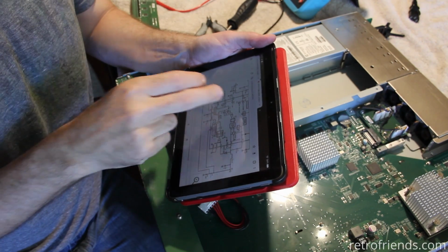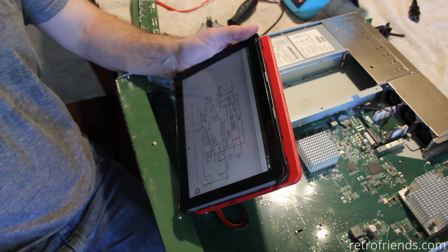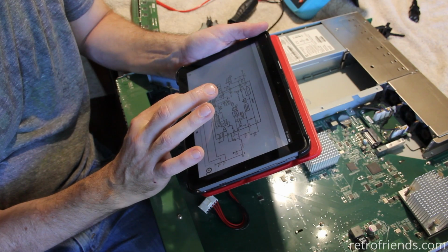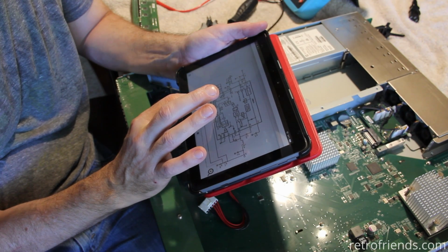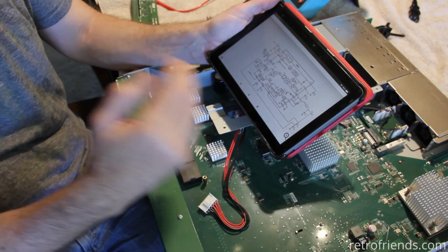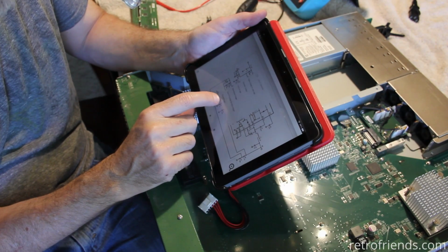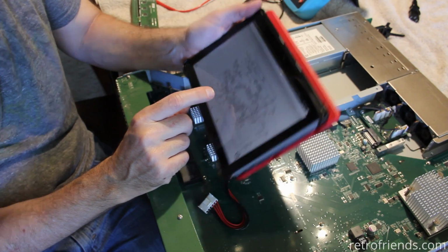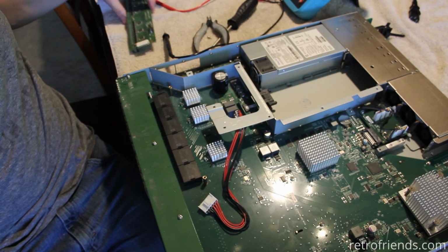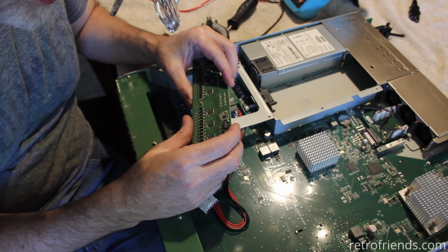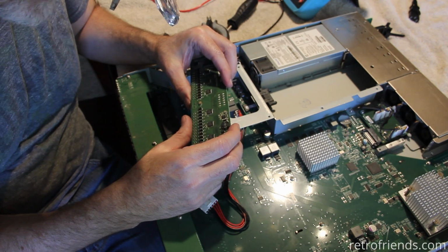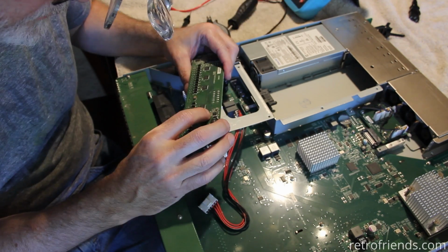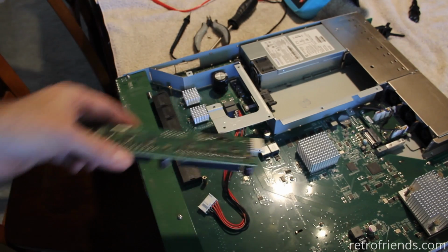I mean, that thing was tiny. But hey, you're putting 56 volts into it. Pin 4 is the sink, and that kind of looks like the pin 4 side of it. So maybe 56 volts went into pin 4 or pin 2, and that would have done it. That stupid little solder ball. That thing was pretty microscopic. Wow. All right, well, that points me in a pretty good direction. So I'm going to order another one and replace it, and we're going to find out what happens.